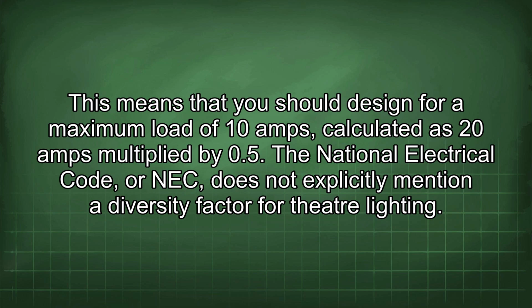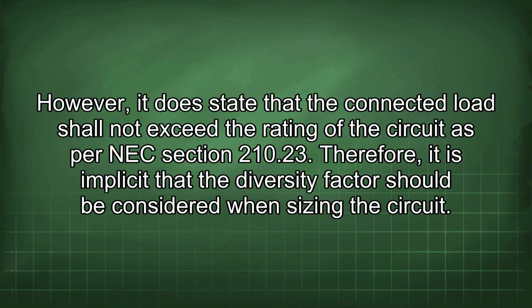multiplied by 0.5. The National Electrical Code, or NEC, does not explicitly mention a diversity factor for theater lighting. However, it does state that the connected load shall not exceed the rating of the circuit as per NEC section 210.23. Therefore, it is implicit that the diversity factor should be considered when sizing the circuit.